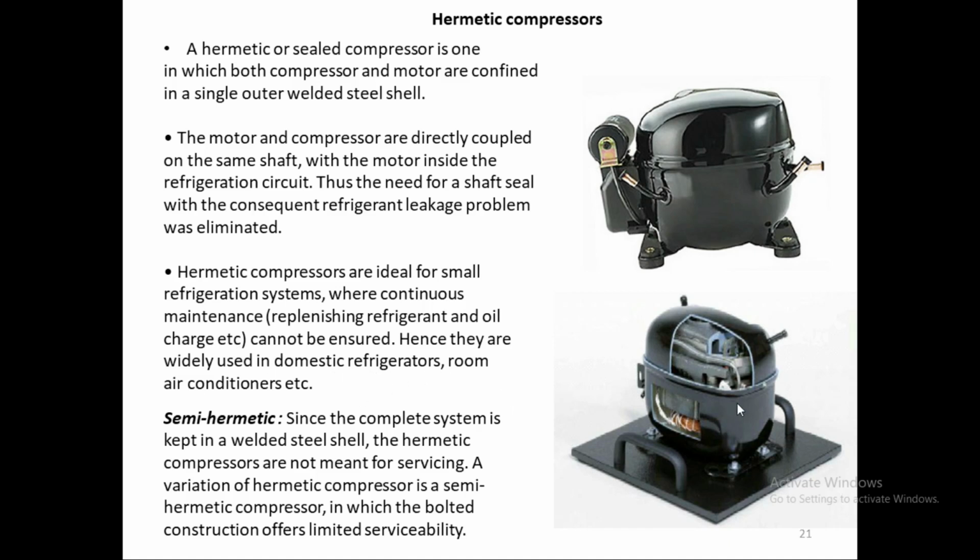The lubricant which is required by the moving parts of the compressor is also inside this compressor. Where you see this winding here, the lubricant is basically also at the same place, which is lubricating the compressor moving parts, piston and cylinder and other moving parts in the compressor. Mainly piston and cylinder, it is lubricating that, and at the same time it is providing some cooling to the motor also, which is dissipating heat. Okay.